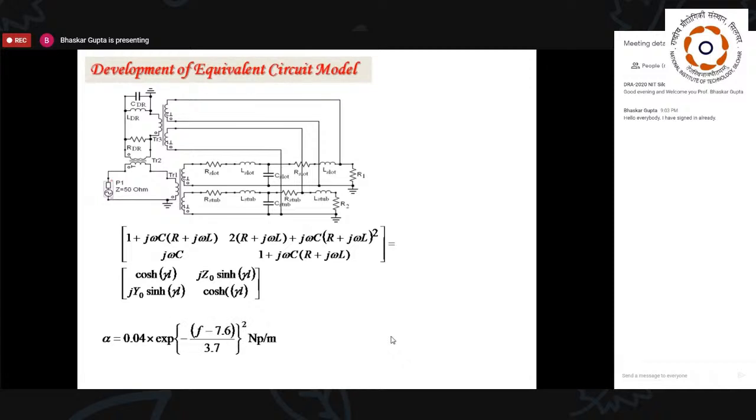Here we have to find out the value of the attenuation coefficient, which we obtained after computation through all our earlier results through curve fitting, given by this formula. By using them, R of course is, as you see, just the resistive part of that transmission line structure corresponding to attenuation, plus a part corresponding to the skin surface resistance, which is responsible for current flow within the skin depth.